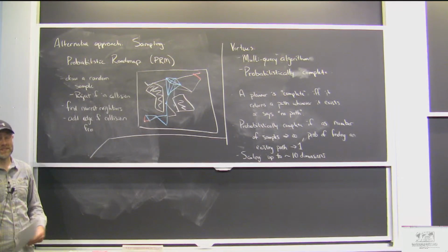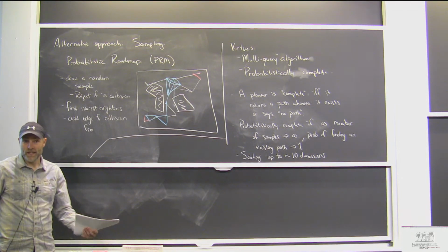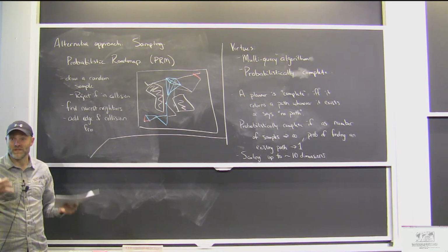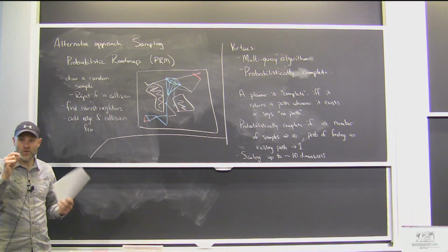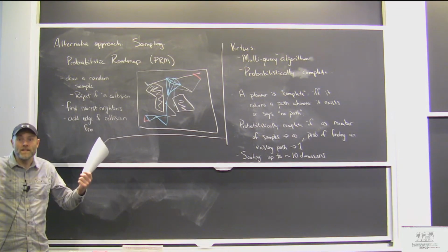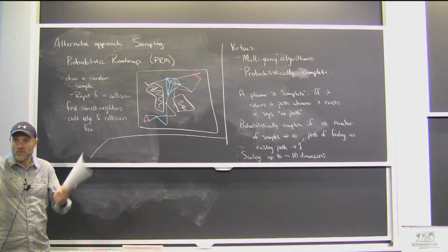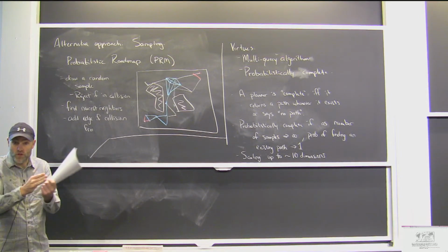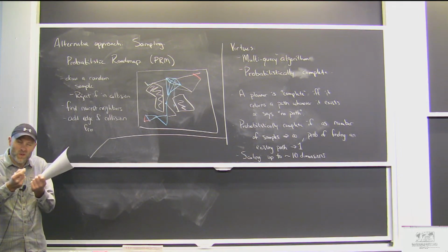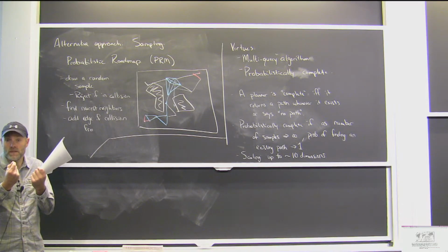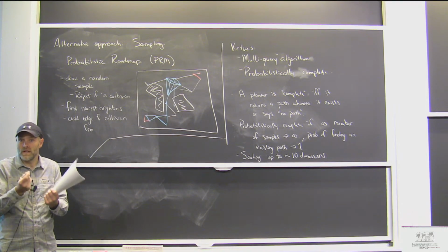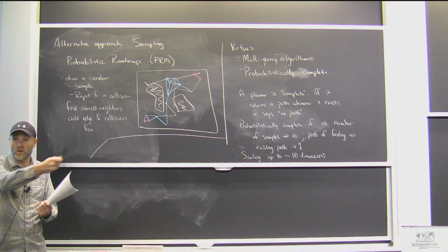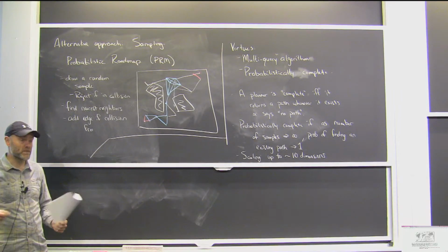That sounds like such a silly thing to point out as a virtue, but it bugs me deeply that our trajectory optimization algorithms typically don't have that property, right? In trajectory optimization, you say, I've got n equals 41 samples. I'm going to move them around and try to satisfy my constraints. And maybe I'll stretch and shrink the path between them. But something is fundamentally missing: we have to encode ahead of time exactly the number of steps it's going to take to get to the goal, even though the goal may be in very different locations, and we might have to figure it out.